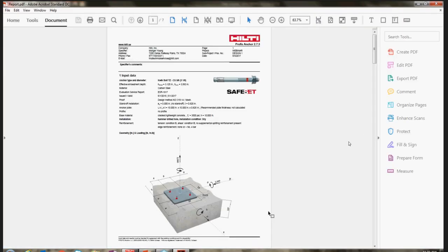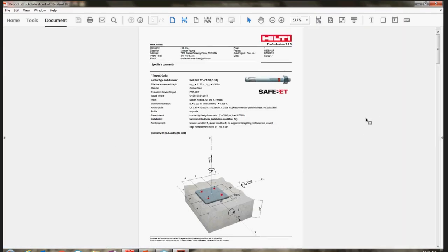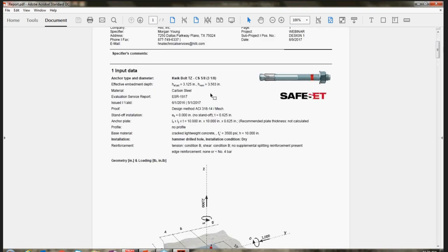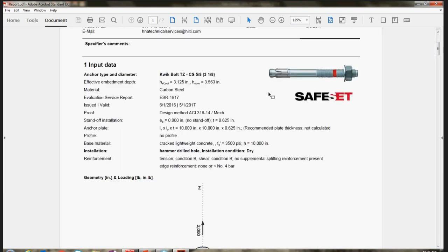And the last tab we're going to look at before we begin modeling on the software screen is going to be the Loads tab. Very important. We came to this tab when we made the first change. We're just verifying that we are using ACI 318.14 and that we are going to do static design. And you'll note this is not activated on the seismic design. We're going to do that later here in the second example. Okay, so we're done with these 5 tabs.